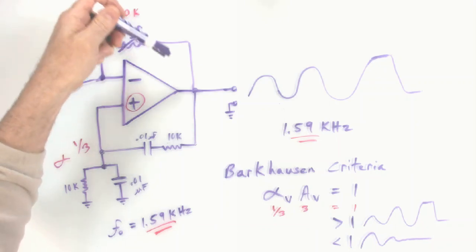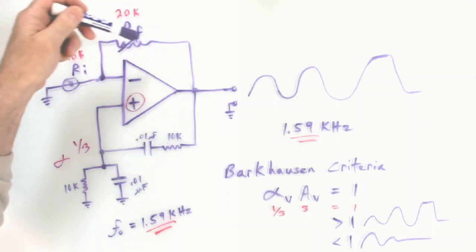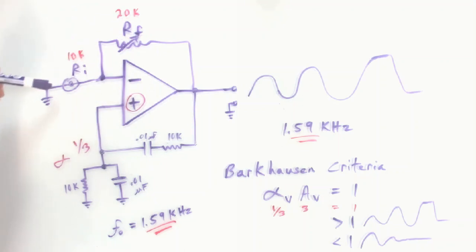And vice versa. If the output would try to decrease, so would the voltage and current. And especially through RI, a decrease in voltage and current means its filament resistance goes down. So RF over RI, which is the gain, goes up. So it'll give a little boost to the gain. So it'll find itself a self-regulating circuit just with a little lamp.